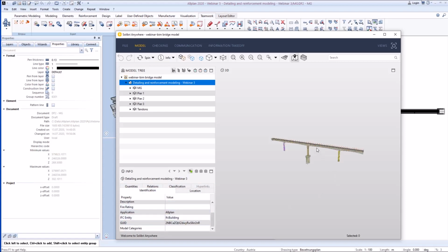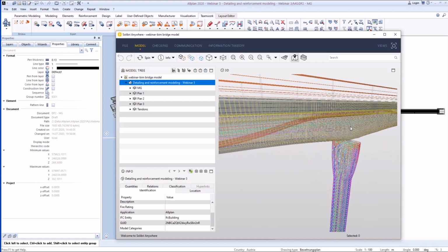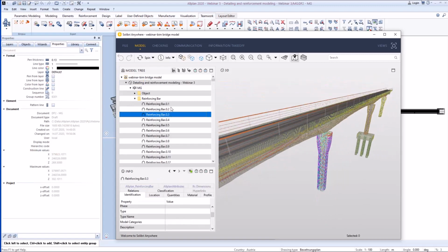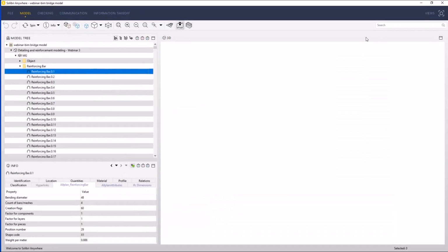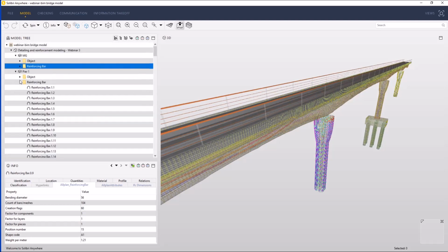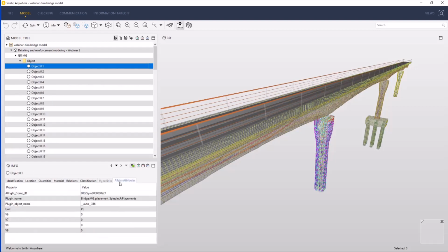As we can see, the complete information from the building structure of our project is transferred to the IFC file. We can also see Allplan attributes, which are all grouped under the map Allplan attributes and can be checked and controlled for each specific element of the bridge. In the case that special mapping of attributes has been done during the export of the IFC file in Allplan, we would be able to see here user-defined maps where attributes are classified and saved.